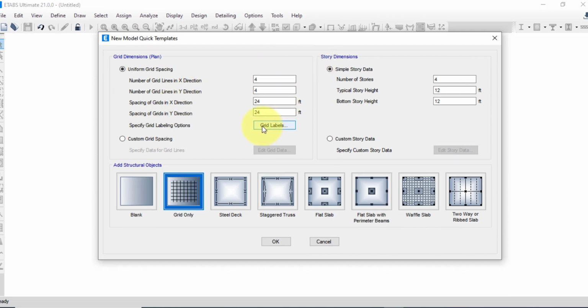For the analysis of a truss, we know that in ETABS the z direction is vertical, and in the horizontal plane only the x and y axes lie, while the z-axis lies in the vertical plane. So in this software, for the analysis of trusses or frames, we will use our z-axis as our y-axis. I will show you later how.